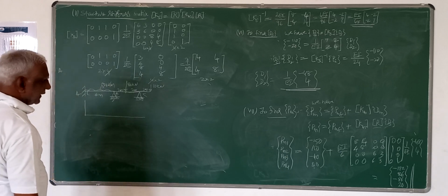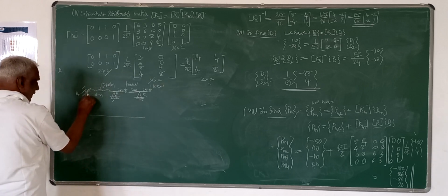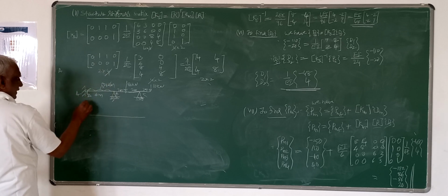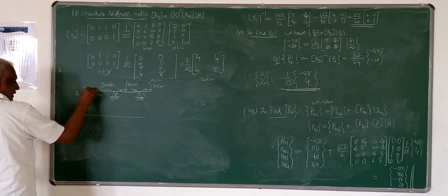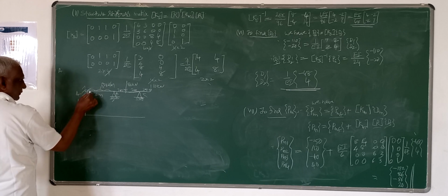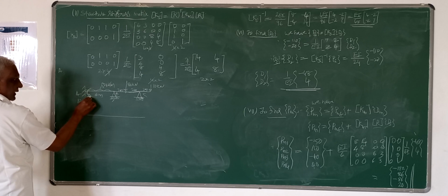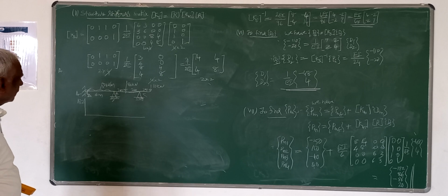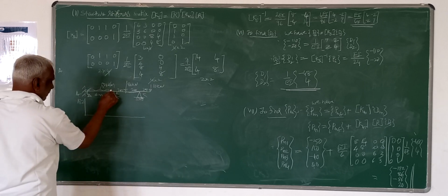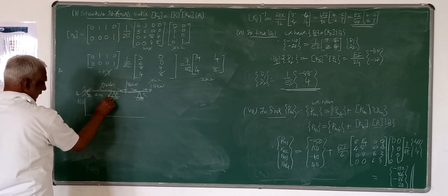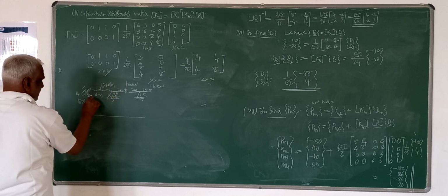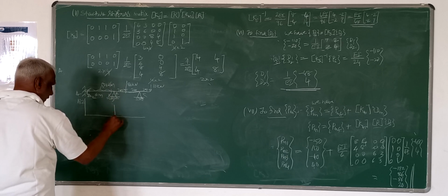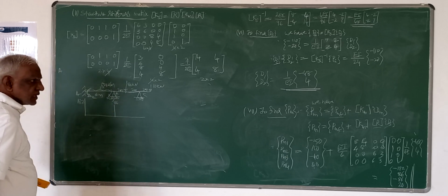It is 182 negative, which means whatever positive direction, clockwise, I have taken, I have to reverse it. So that's why I am plotting on this right side of the arrow. The arrow side is right, always we plot on the right side. That's 182, PM1, and PM2 is positive, it is 86. Here also I have to plot it on this side, 86.